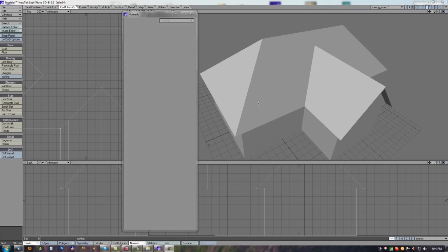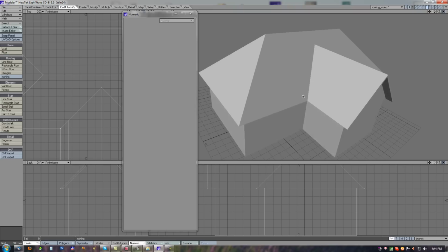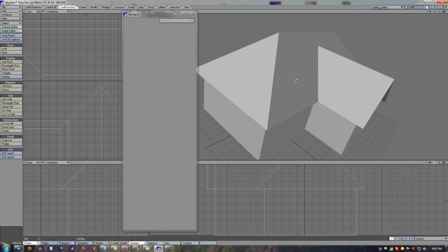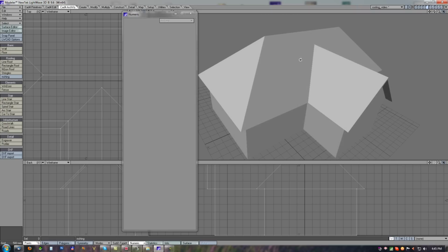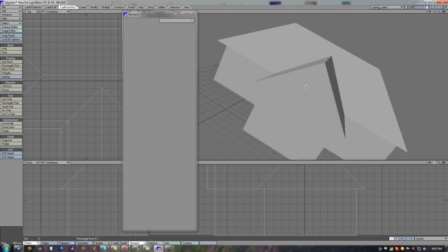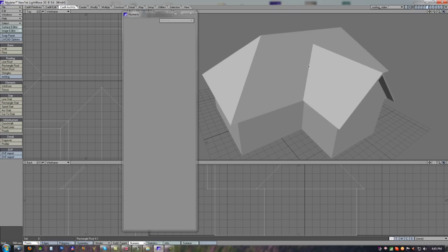Shingle tool. In the current version, LwCad 4.1, we have a new tool for automatic placement of shingles on existing roof objects. As an input for this tool we need to have some roof object, a polygonal object. It is better to use roofing tools from LwCad to model it, but we can use another method or use an already existing roof object, but we have to be careful about polygonal errors and no holes on the roof.